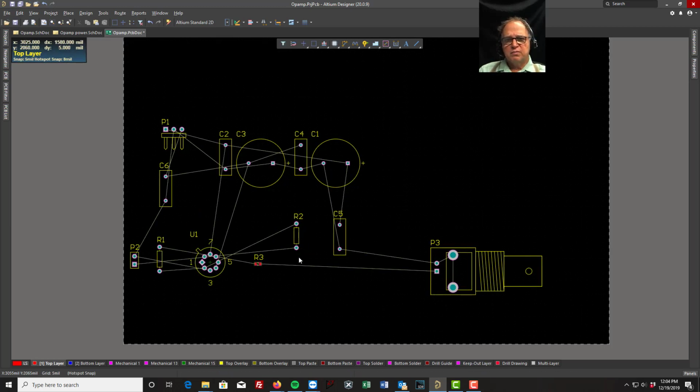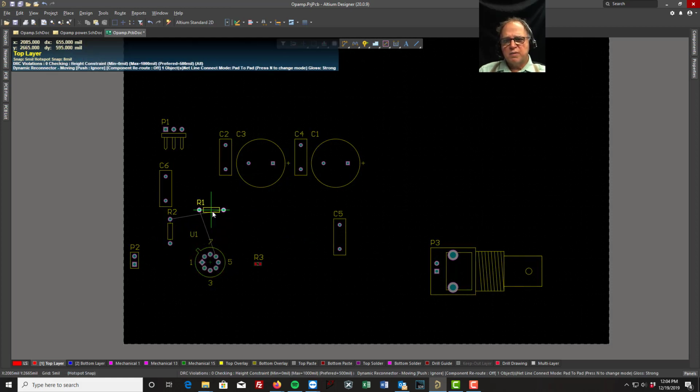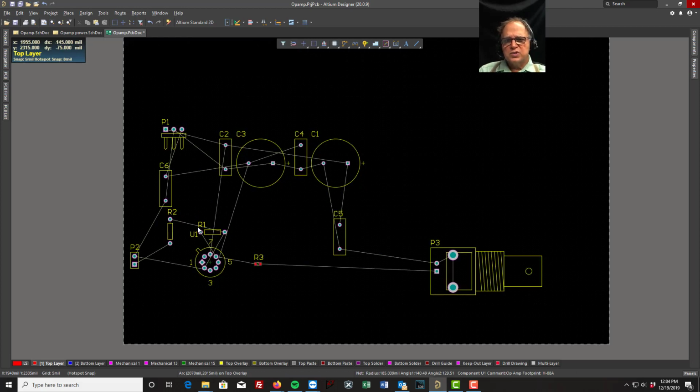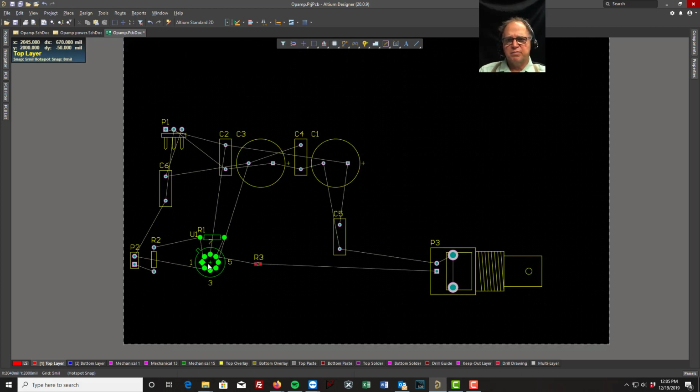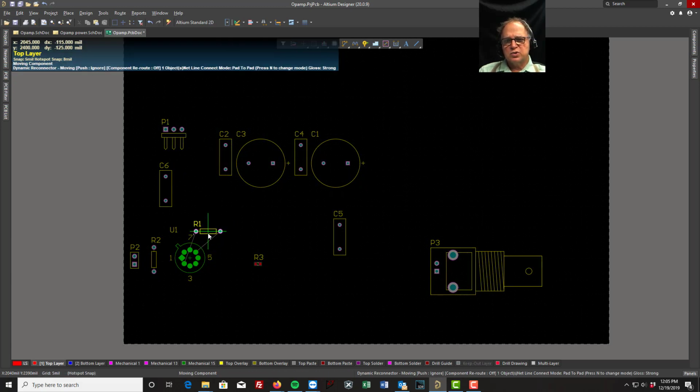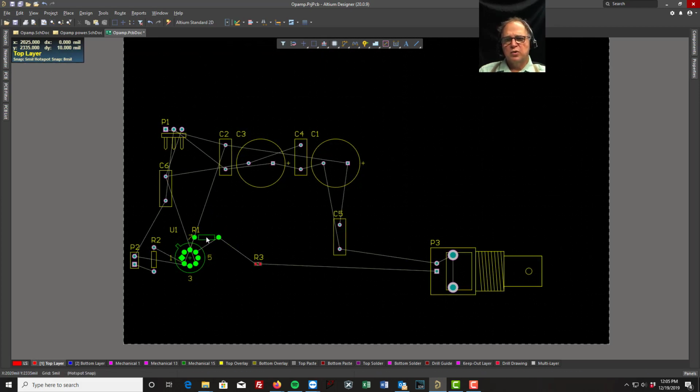Let's see. Here's our input resistors and feedback resistors. Now notice when I put this resistor here, you see that this line has to cross this line. Those are the net lines. It's going to be easier to route the copper if I just rotate that so they don't have to cross. Same as if I did this and I had this guy sitting over here somewhere and look, the lines have to cross. I don't want to make it hard, so I'll just rotate the part. That's your job as the engineer when you set this up, to make it easy to route. Now see where it turned green? I had that resistor too close. If it's too close, green tells me there's a problem.